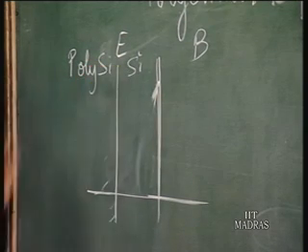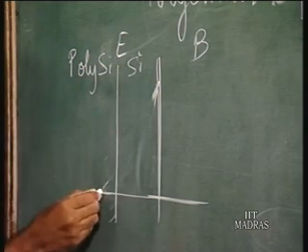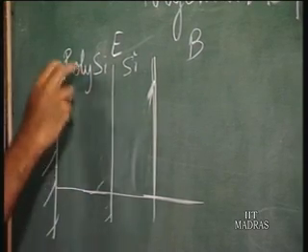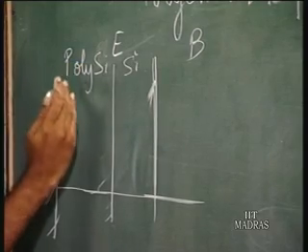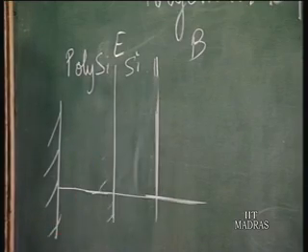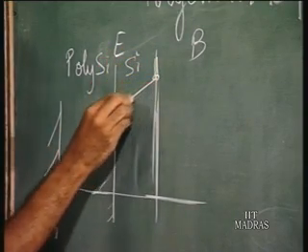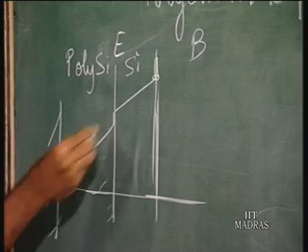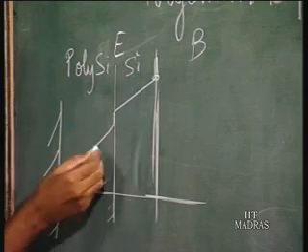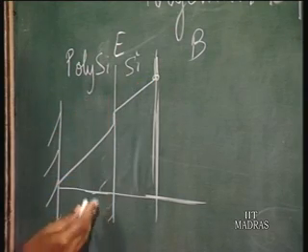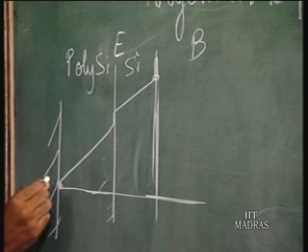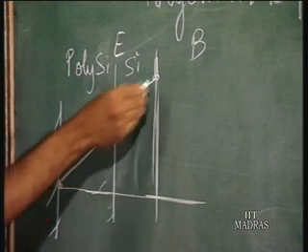So, you have a silicon polysilicon interface, and then you have the metal. If you have such an emitter structure, the entire emitter now consists of two parts, one is polysilicon and the other is silicon. The profile is something like this. Here you have a small difference because there is some recombination at this interface, but the recombination is very small. So, in fact, the carrier concentration is going to go to 0 at the polysilicon metal interface. So, the profile is almost like this.